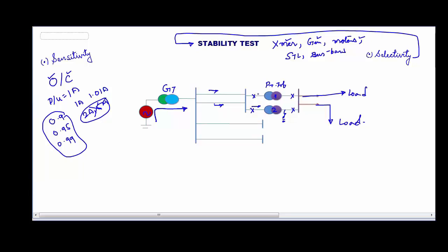It will take up this path, and it will take up the path of transformer 1, which will be added to this low voltage bus bar, and again it will take up this path. So this division is totally on the basis of the impedance of both of these two transformers, and about these two bus bars, if they have connectivity with the system. If we have a system with a large number of generators, transformers and transmission lines in it, and it is connected in such a way, they are also going to feed the fault.